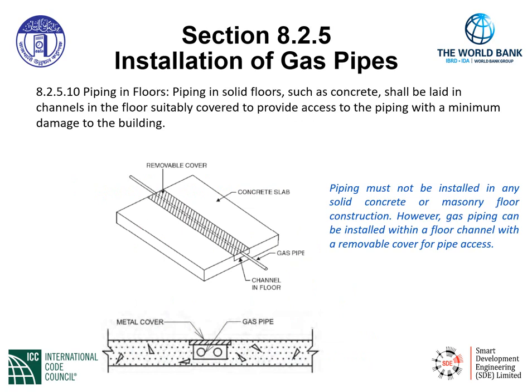We are permitted to install piping within solid floors. Section 8.2.5.10 gives us a requirement to install the piping in such a manner. Piping in solid floors, such as concrete, shall be laid in channels in the floor suitably covered to provide access to the piping with minimum damage to the building.